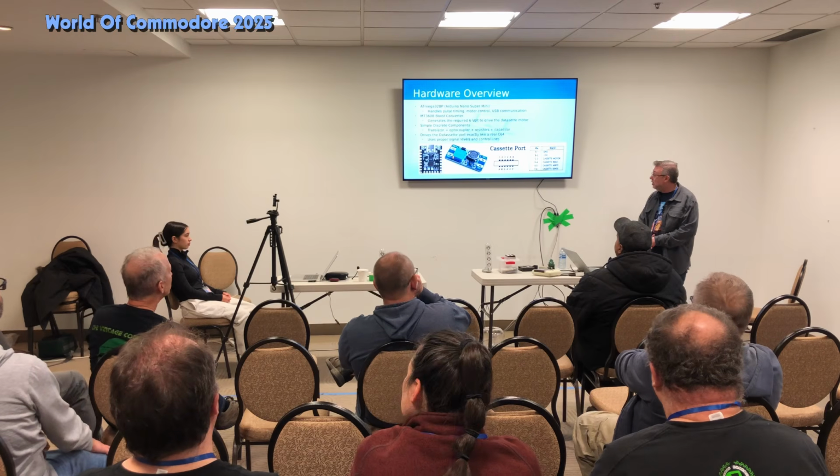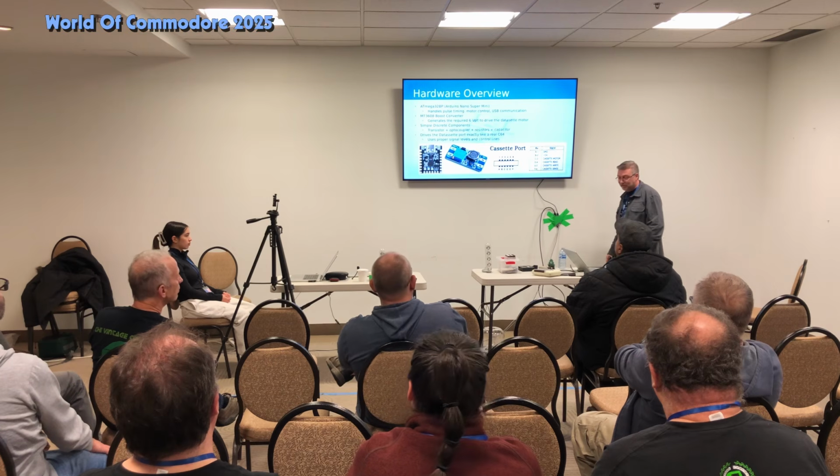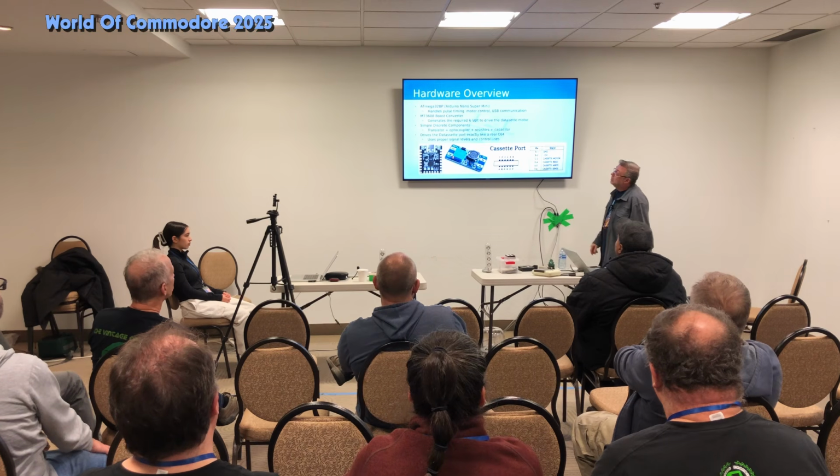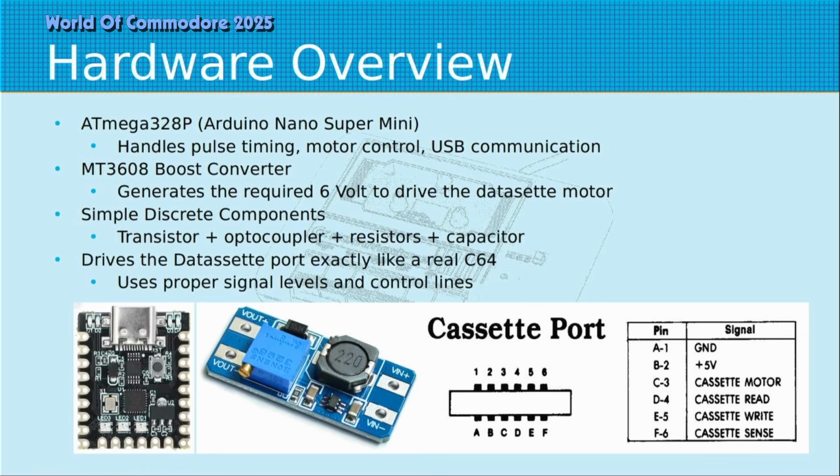So a little bit in terms of hardware, I've decided to design the PCB with modules in mind. The first one on the left is called an Arduino Nano Super Mini. It's available on AliExpress, DigiKey, most distributors. At its core, we have an ATmega chip. It's the brain of the system. It handles the pulse timing, motor control, and USB communication.